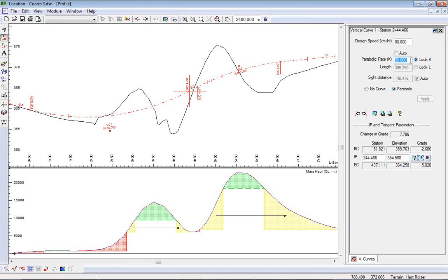You can tell your bulldozer operator, okay, if you move 50 meters, you change your grade by 1%, he's going to build you a parabolic curve. Which is why they chose parabolas when they decided this was the standard way to build roads. Because it's easy to actually go out in the field and build one.